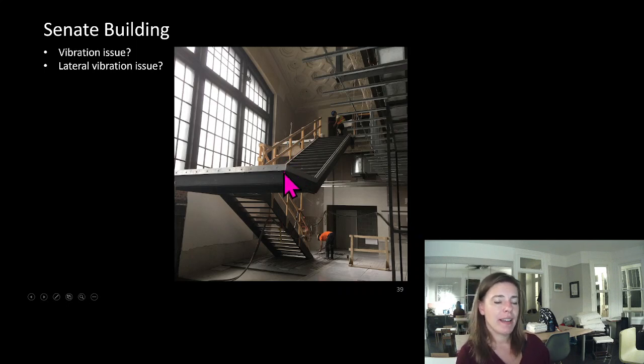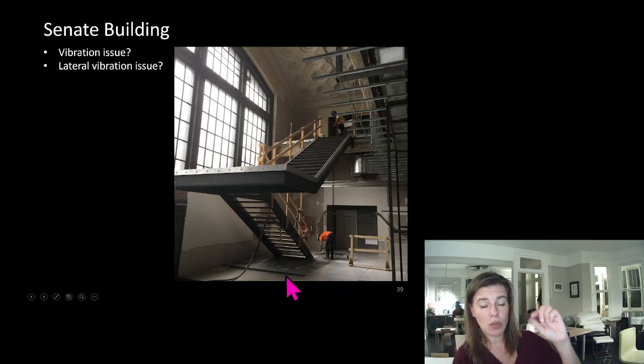So everybody went to site, and I'm talking to them on the phone, and one guy, I think his name was Mike. Mike's like, oh, I weigh 250 pounds, and a kilonewton is 225 pounds. So we got Mike to go stand here on the corner. Well, first they hung a string with a plumb bob and cut it off so that it was perfectly on the ground. We then had Mike go stand on the corner, and we saw how much the string shortened, or basically how much string pooled up on the ground. You couldn't measure it. It was less than a millimeter with Mike standing on that corner.